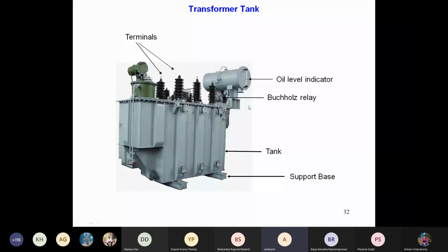So in that case, if the oil is not able to dissipate the heat to the atmosphere, the inside is getting heated, and it may even lead to damage of the transformer. So to prevent that, they will basically stop the transformer. The input switches will all be opened so that the power supply is stopped.